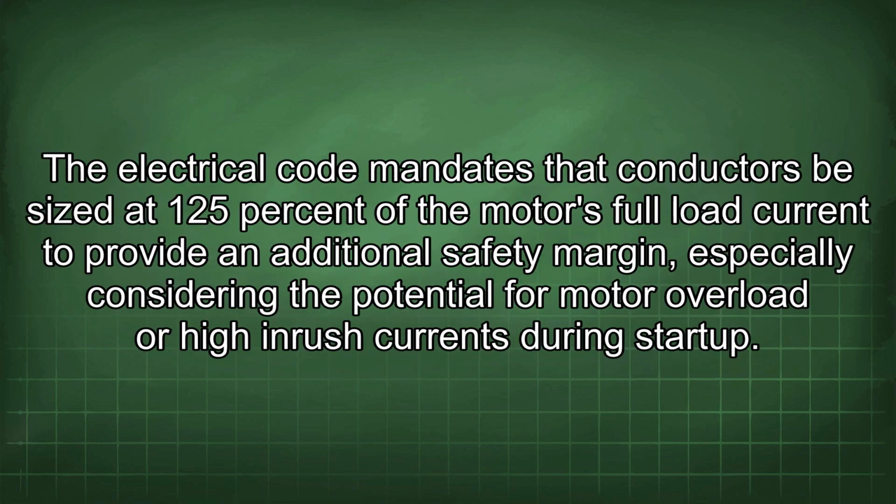The electrical code mandates that conductors be sized at 125% of the motor's full load current to provide an additional safety margin, especially considering the potential for motor overload or high inrush currents during startup.